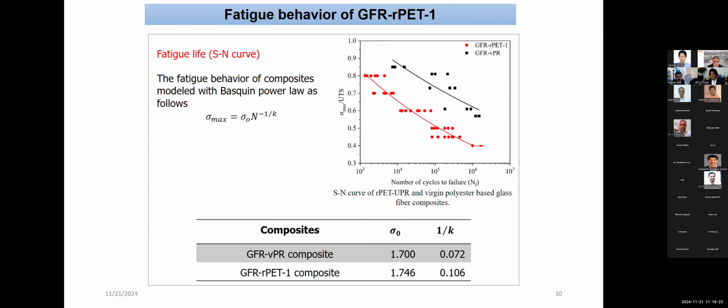If you come to the results here, as we expected, this is the typical Basquin equation, which was discussed maybe day before yesterday also, a very old equation, but still used for typically signifying the S-N curve in S-N curve studies. So what we observe is that the red line is our material that we tested in the lab, and the black one is from a reference paper by Vassilopoulos, a very old one. I remember, I think it's in 2008 or 9 somewhere they published this paper.